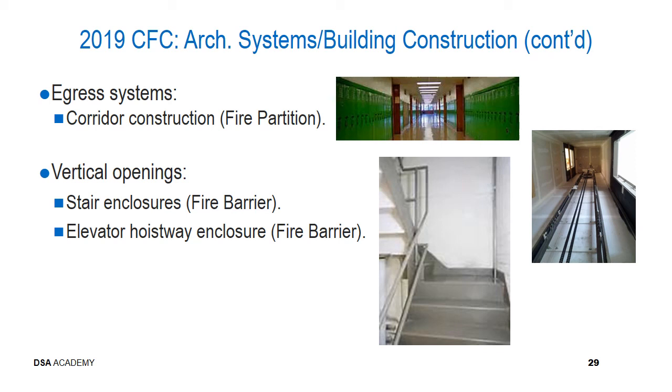Further, in Section 403.2.3.1 for wall assemblies, the code states, the wall assemblies making up the enclosures for interior exit stairways and elevator hoistway enclosures shall meet or exceed the soft body impact classification level 2 as measured by the test method described in ASTM C1629.